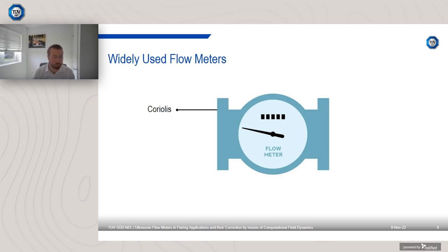We also have the turbine meter, and these are a velocity type flow meter and work on the principle of magnets. Now, as you might expect, turbine meters have blades and are therefore intrusive. Again, that's not what we want, and we also need to regularly maintain these meters because you either need to supply the meter with oil, or you might need to carry out an oil service to make sure it's operating in tip-top condition.